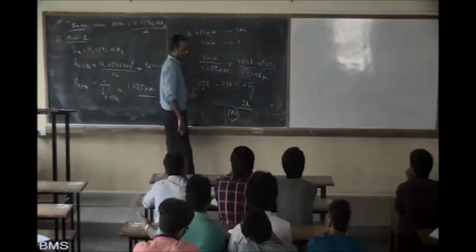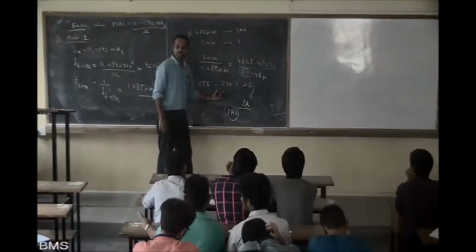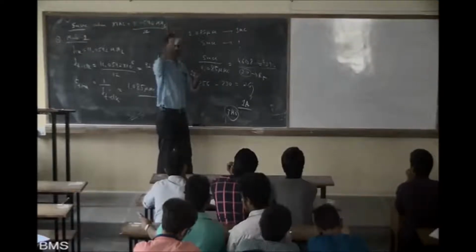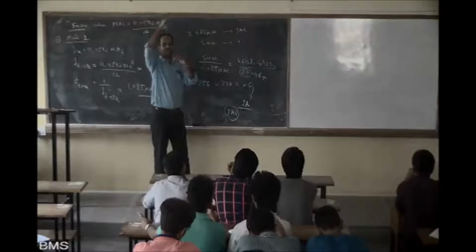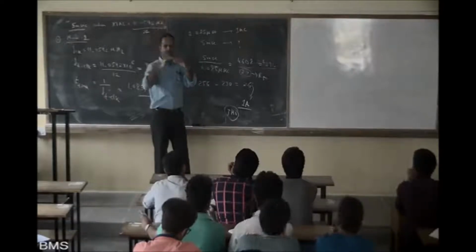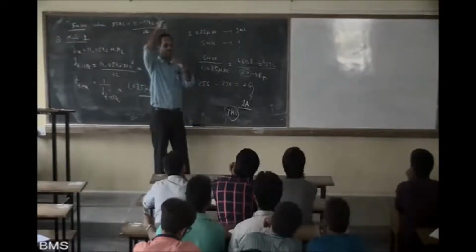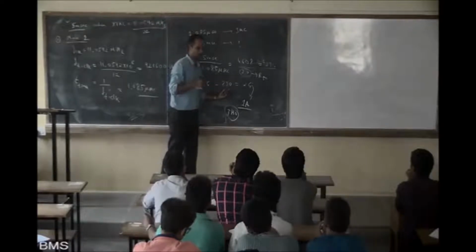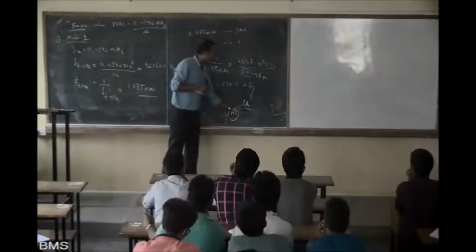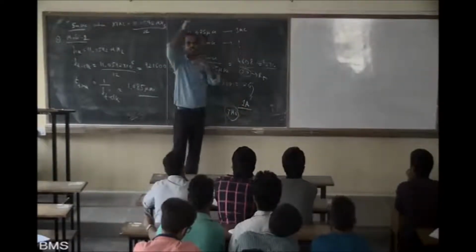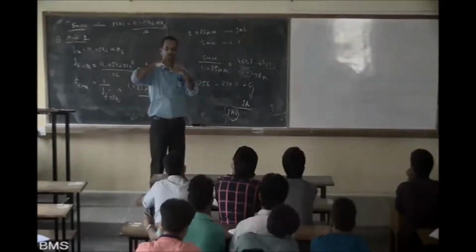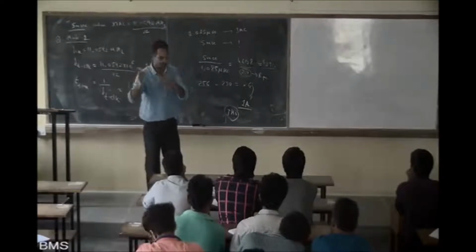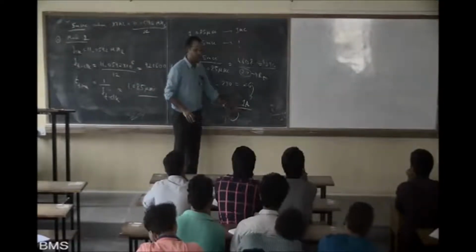What is the highest value? Why should you subtract from the highest value? Because your counter is an up counter. From the given value, it will count up to the maximum value. If you start at 1A and reach FF, then your count value is 230. Is it clear? Because it is only an up counter, you have to subtract and get a value.